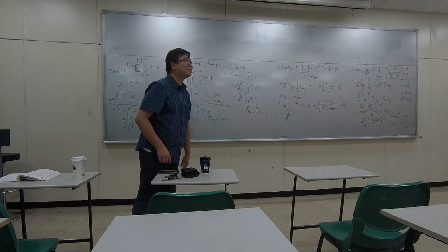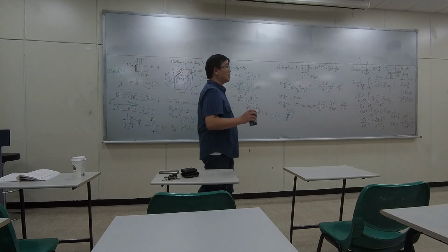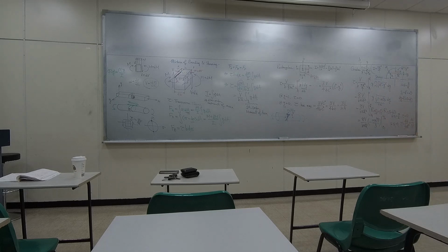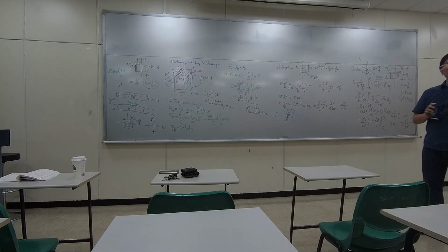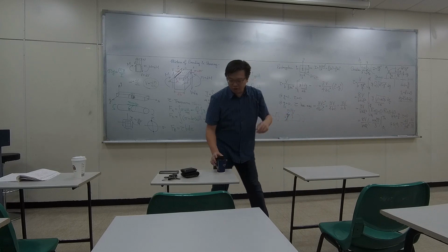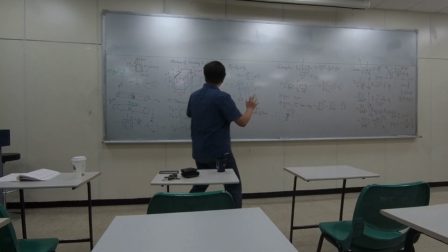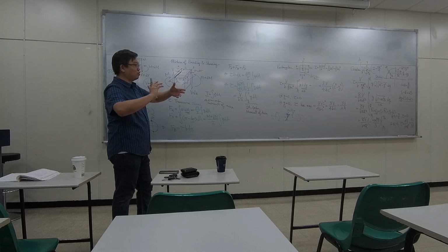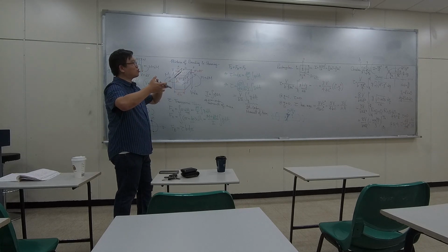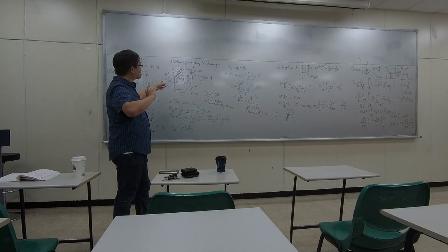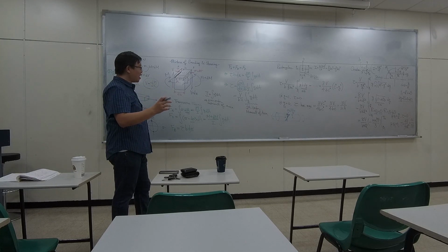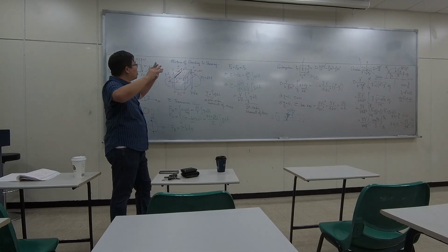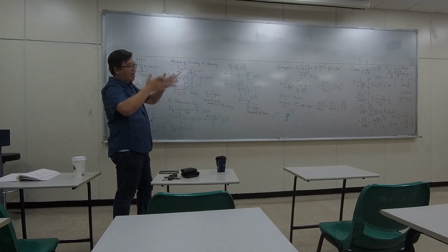Is there a difference between this formula and the formula you give us? No, that's another story. In this problem, we never talk about torsional shear. This is pure bending, and due to some reason, you have some forces somewhere, so there is shearing force up and down.